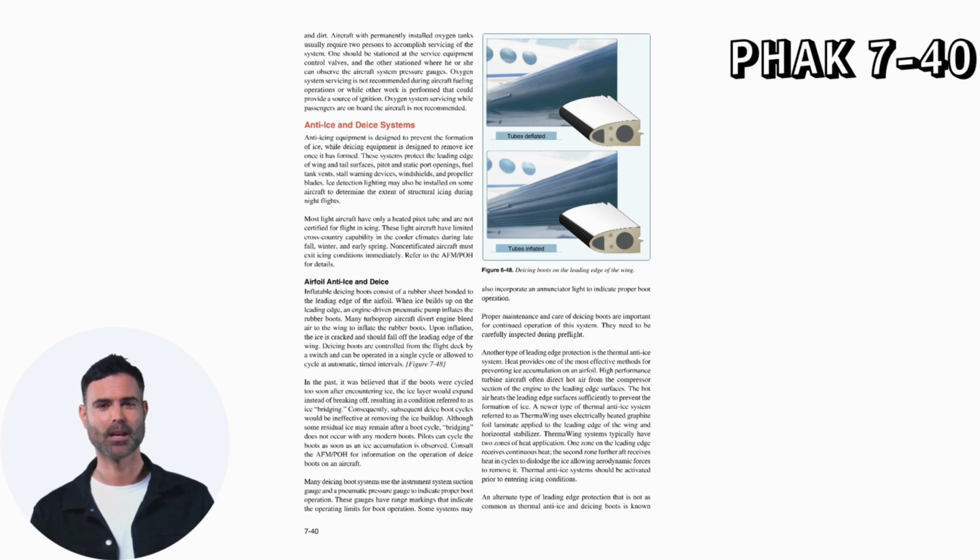Most light aircraft have only a heated pitot tube and are not certified for flight in icing. These light aircraft have limited cross-country capability in the cooler climates during late fall, winter, and early spring. Non-certificated aircraft must exit icing conditions immediately. Refer to the AFM-POH for details.